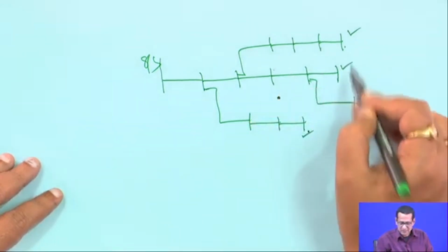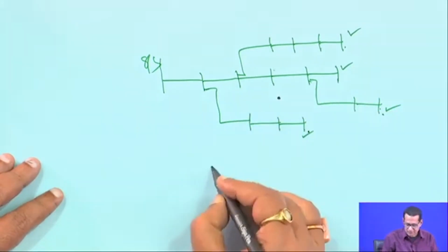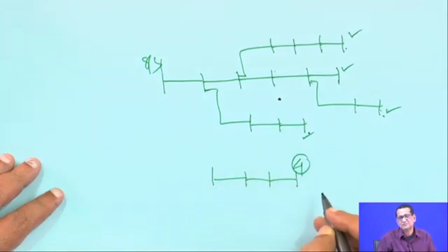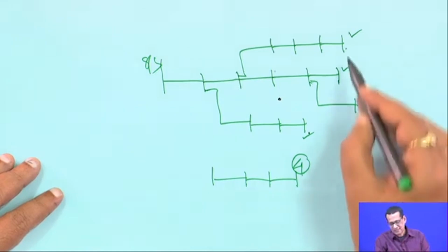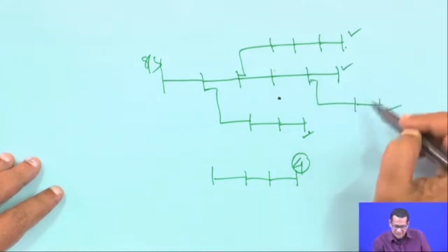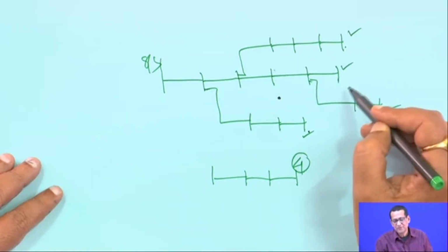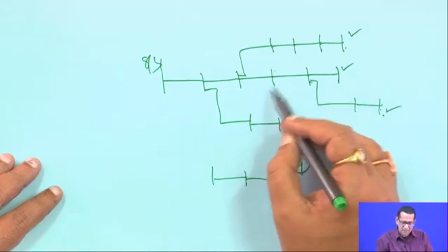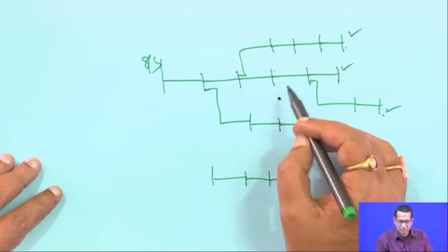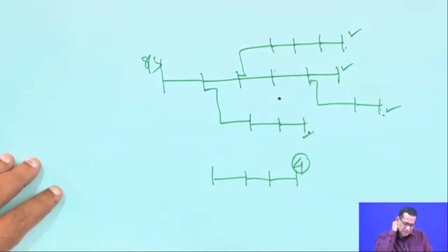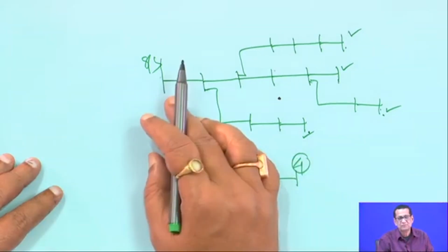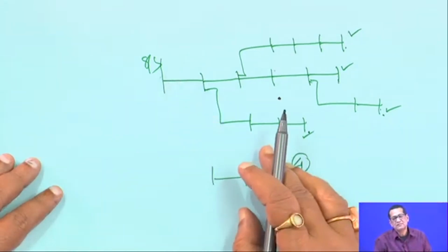It is not that... the example we took is a very small example, only 4 nodes. So, this node is actually sensitive to the voltage collapse. In reality you may have many laterals, but that does not mean any of these lateral or main feeder end nodes will be sensitive to the voltage collapse. It depends on the load, the R and X values of each branch load, and at the same time also the substation voltage level. Many factors are there.